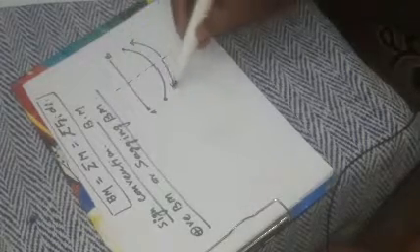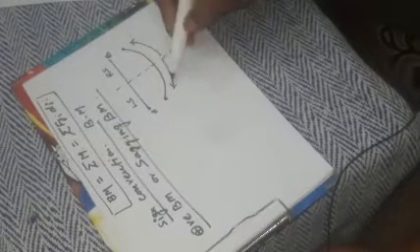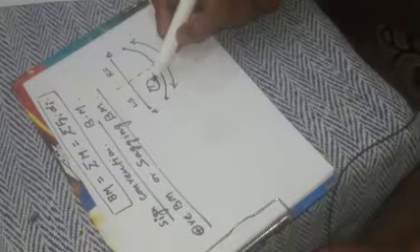And in this case, beam bending moment for left segment, this is your left segment and this is right segment. When we are moving for the analysis from left into right hand, then this moment, this arrow, when we will complete this arrow, there will be symbol like this way, clockwise. The clockwise moment is positive for left segment, and similarly when we complete this curvature, there will be anti-clockwise rotation. Anti-clockwise rotation for right segment is positive.